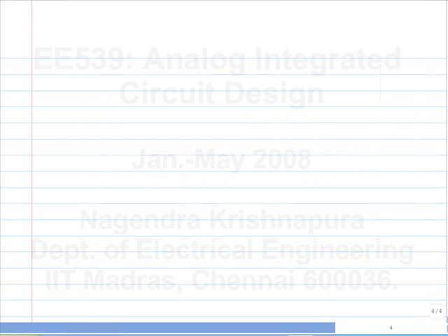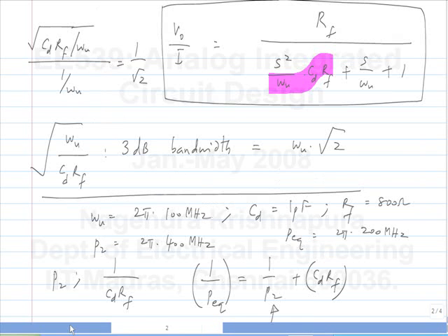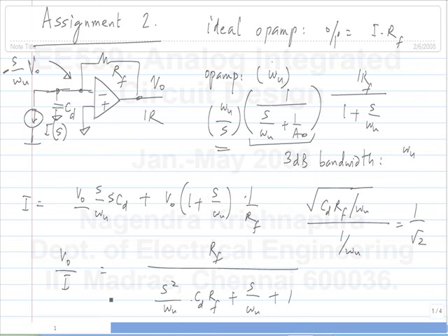Then the next part is, so basically here you see that there is a trade-off. Trade-off meaning once you have a diode with some capacitance, okay, your RF is limited to some extent. Okay, you can see that if you choose, let's say, a very high frequency op amp, it's not very useful because the feedback pole is introduced and the bandwidth you get will be omega u times.